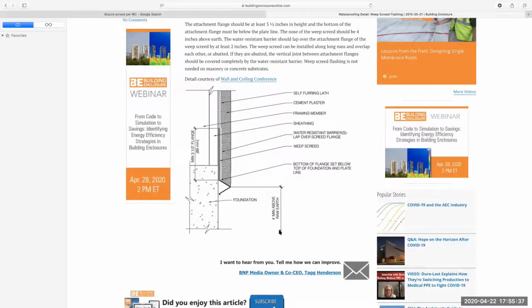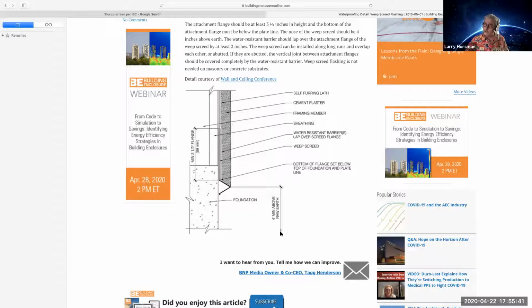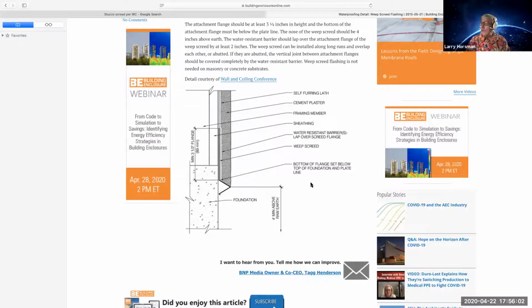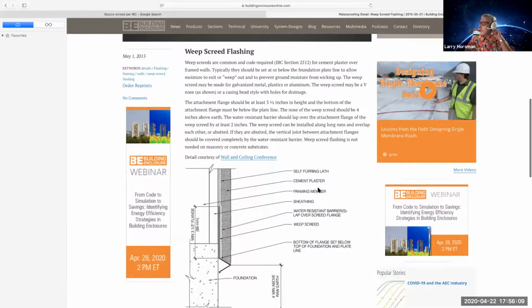And then here's our 4 inches above the dirt. And if you go into the code, it's 2 inches minimum above concrete. That's why I was saying early on when we were talking about this, I was concerned about the step down slabs that were only 3/4 of an inch, because if we have stucco over those, So it is saying 2 inch above the concrete, huh? Yeah, that's what I'm saying. So I'll send this out too, but I'll make a copy and send the other out.